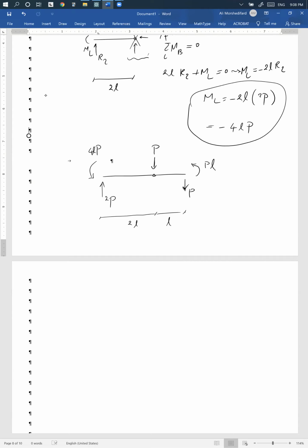All right, so this is the final product for the reactions. I have put all the reactions and external forces. So for beams, N would be meaningless basically because we don't have axial forces in beams, so N is 0 for beams. Be careful that you don't have any axial stuff. For example, in the rope example, do you remember the rope one? We had an axial component, so we had to write N as well. But here it's just a beam. All the forces are vertical forces, right? So you don't have N.